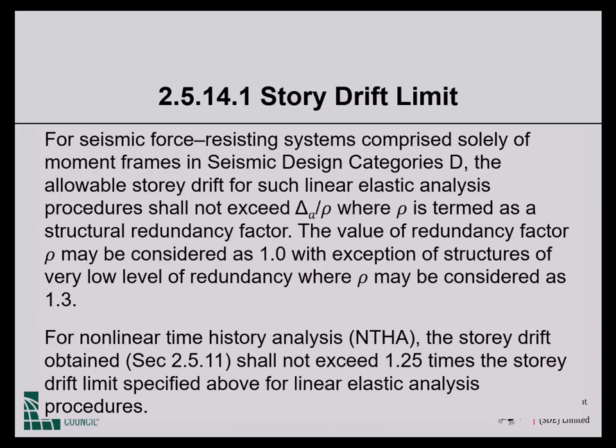BNBC 2020 has none of that. We in BNBC do not have the redundancy factor playing any role whatsoever in the design load combinations, and the code does not even talk about redundancy except here, interestingly. Okay, and what it says is rho.